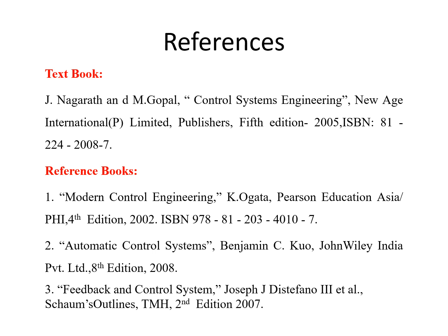You have learned how to find the order of a system by knowing the number of poles, and the importance of the transfer function and poles and zeros in the stability analysis of a system. You have learned three important types of stability: absolute stability, marginal stability and relative stability. Based on these concepts, we are able to analyze whether the system is stable or unstable.